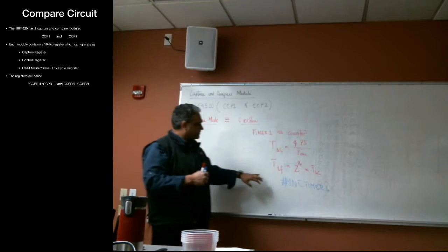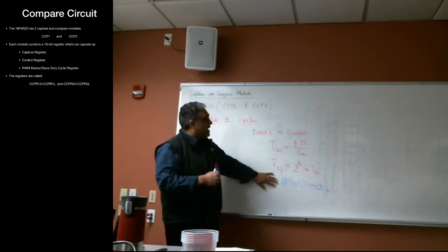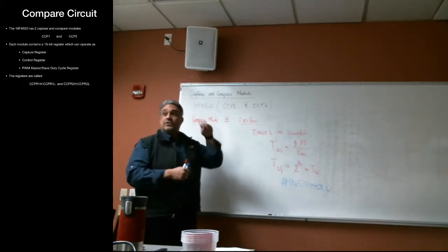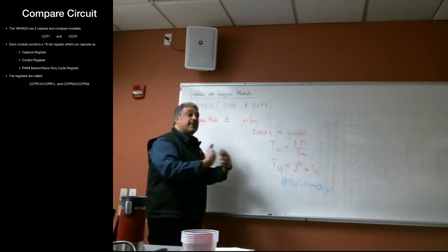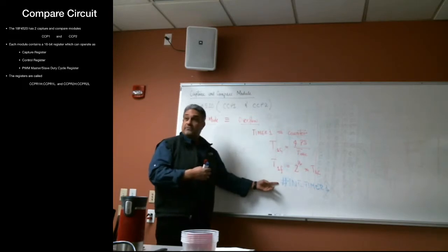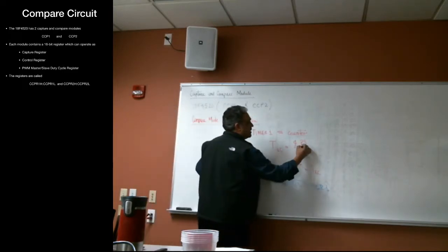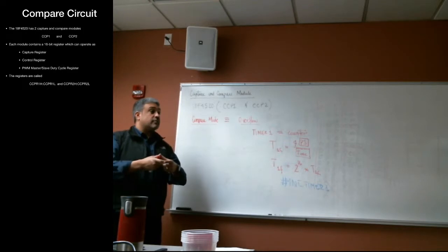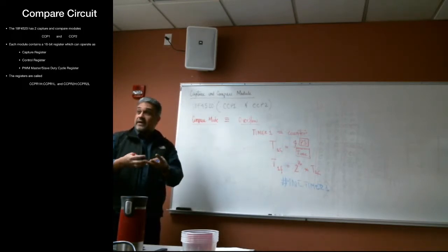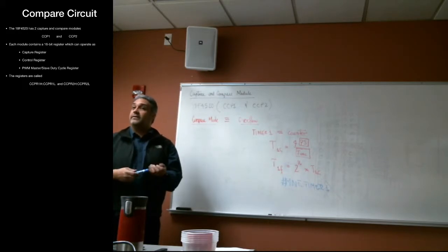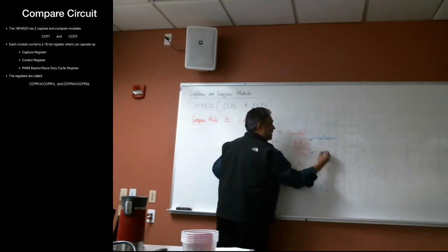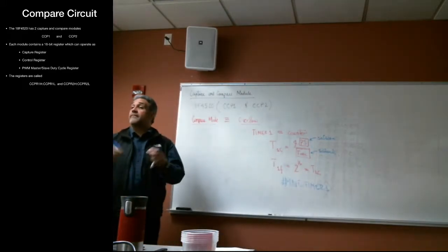All right? Now, what we're going to do is that we are going to expand on this idea. And so if you think about how this circuit operates, there is only 2 variables that can manipulate the period or the frequency of interrupts, right? And one of those values is a prescale value, and the other one is the frequency of oscillation, right? One is a crystal that you actually soldered into your micro, and the other one is a software variable, right? So this guy, you can change via software. Well, this guy is pretty much soldered. And those were our variables, right?